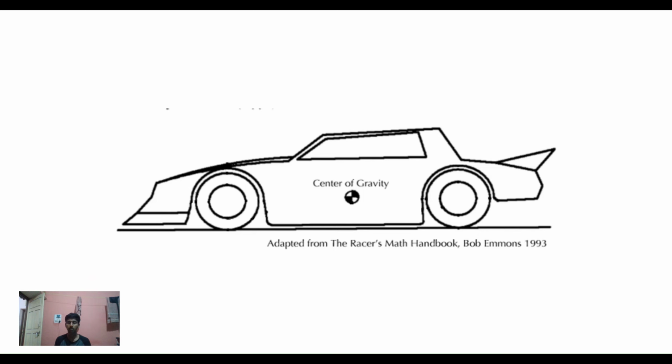By modifying the suspension links, you can lower or increase the height of your chassis and set the CG height to a suitable level. Like I said, the lower the CG height the better, but don't make the suspension too stiff in the process of lowering it. That makes the ride a whole lot more uncomfortable, and that will create more problems later on.